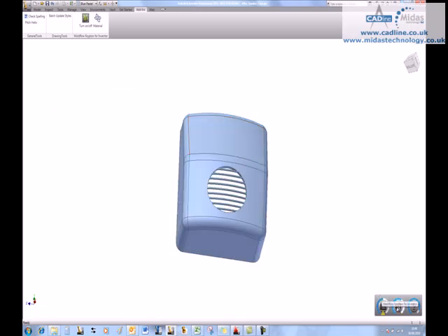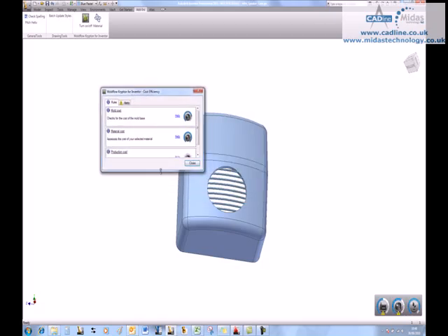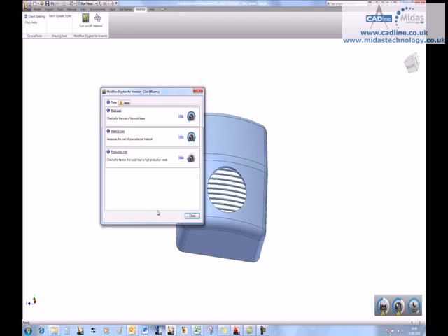Okay, next one being cost, and it runs through and breaks the cost down into the mold cost, the material cost, and the production cost. So you can see that the mold cost is relatively high, the material cost is really high, and the production cost is not too bad. So the alerts: production cost, very high cycle time, and that'll obviously come back to what we've seen under manufacturability. I imagine the mold cost being quite high is because we've got straight walls.